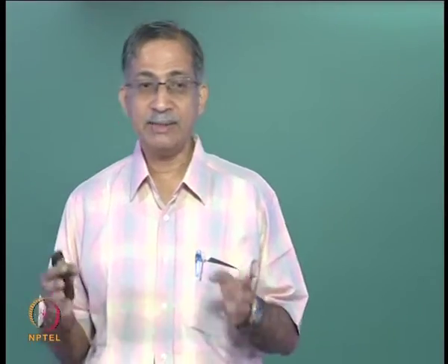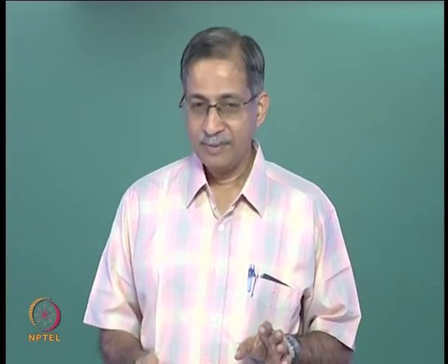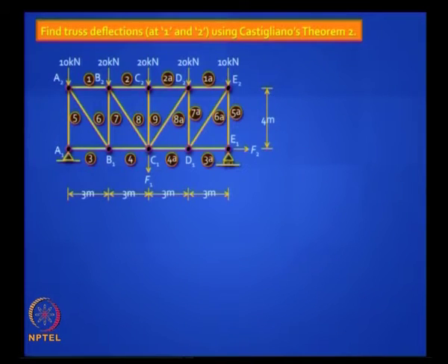When you see a frame, worry only about bending, flexural strain energy. When you see a beam, do that unless the beam is deep. When you see a truss, only axial strain energy. So you can use it to find truss deflections, same method, a little complicated.